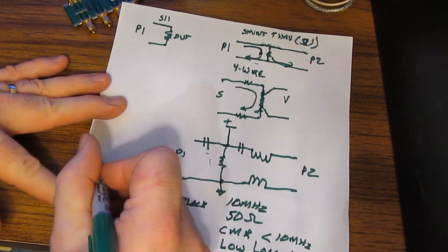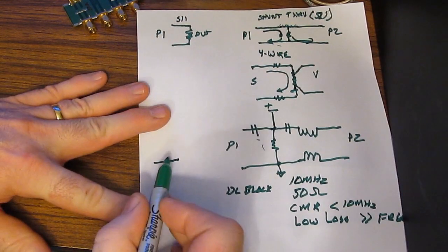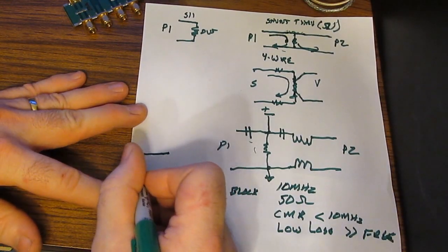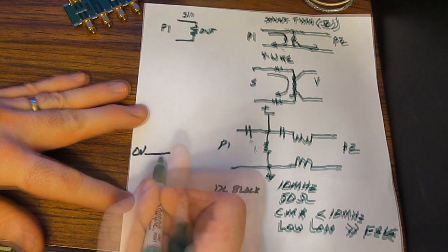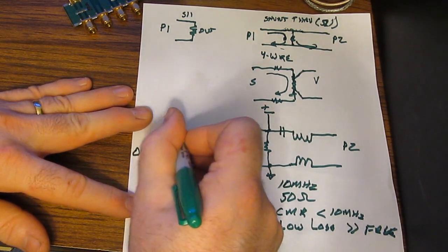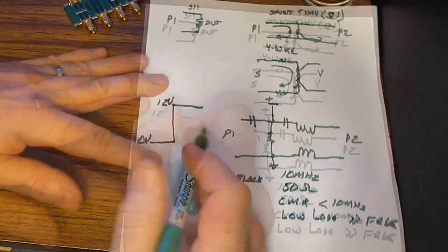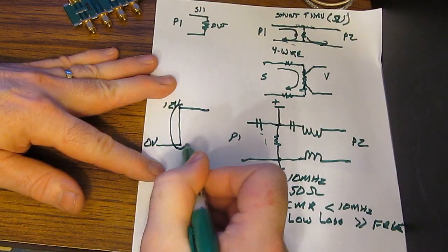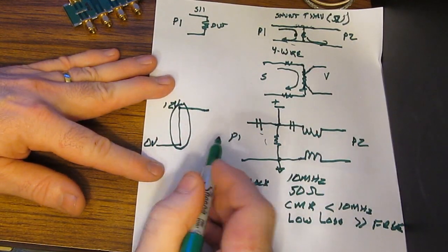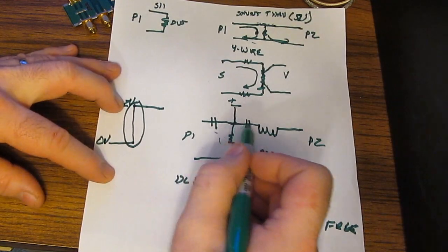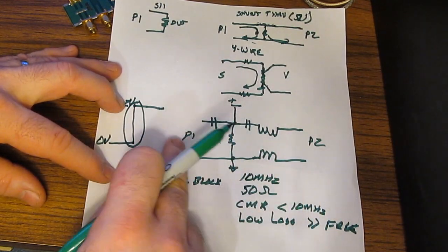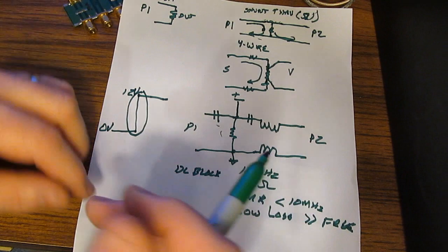So what ends up happening is if we're looking at the voltage with a scope or a meter or something, we're down at 0 volts, and all of a sudden we turn on our PDN, and let's say it goes to 12 volts or something. So the frequency content in this step here when we turn it on could be very high. That can blow right through these capacitors, right into our network analyzer, and take out the front end.